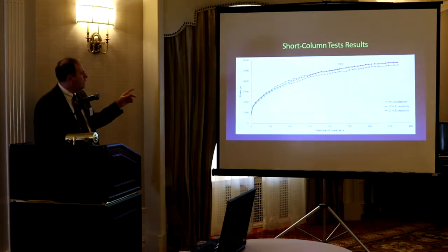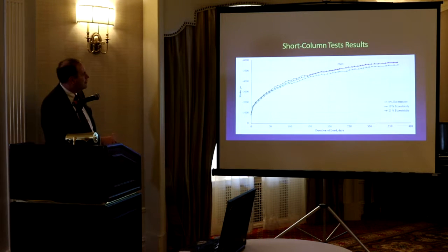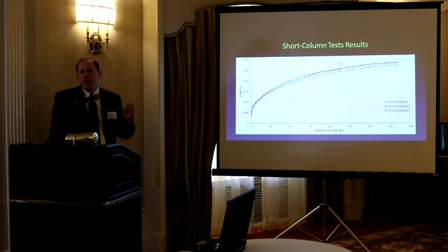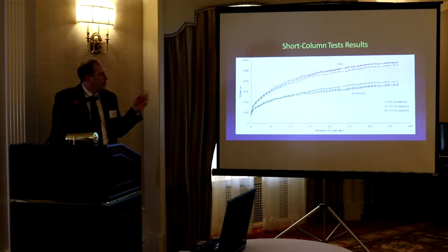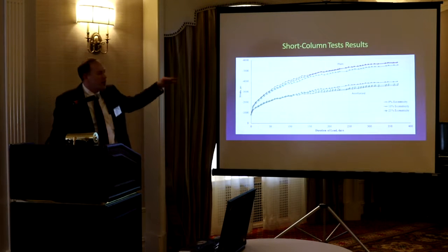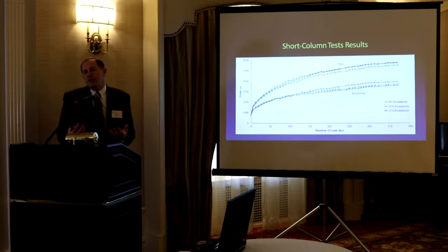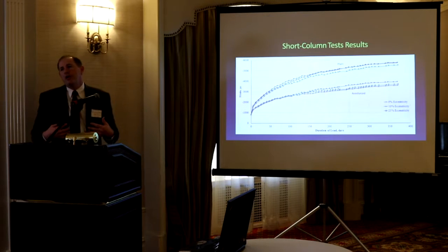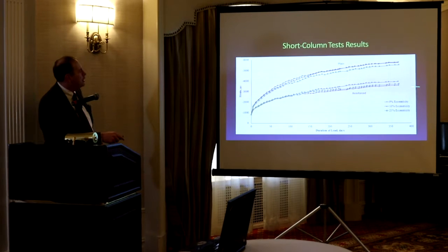So if I take a look at that, this is plain columns. These 3 different eccentricities followed pretty well. The creep did at 50%, holding that worked pretty well. Here's reinforced. It's going to break down your strain because the steel is taking, right? The steel is shedding, the concrete shedding load into that steel. And so you see the reduction here.